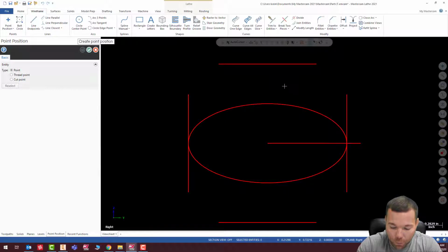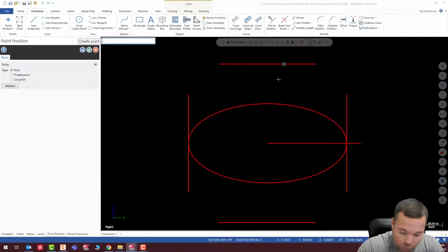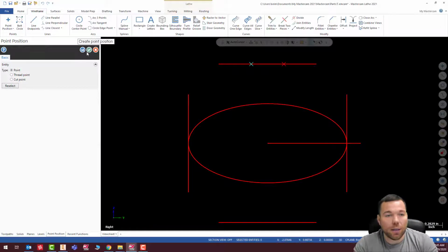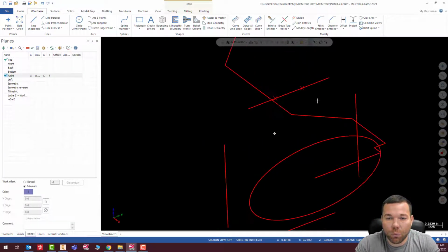So I'm going to go positive x, 0.2057, comma, this is positive 1 inch in the y, so I'm going to go 1.0, and my z is comma negative 0.525, enter. And there's my point. So I'm going to do my other point quick. That's going to be negative 0.2057, comma 1.0, comma negative 0.525. And there we go. So I have my 2 points.